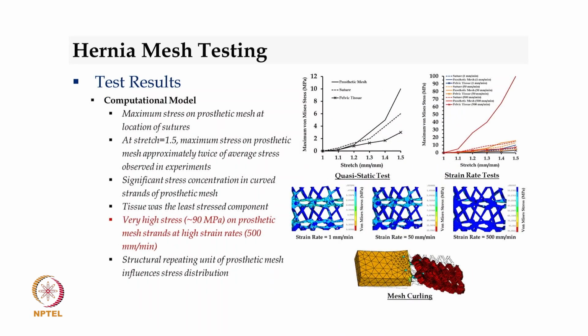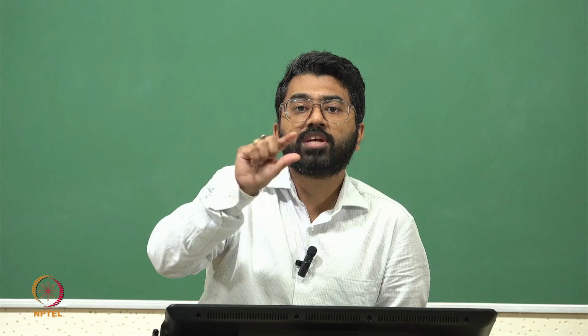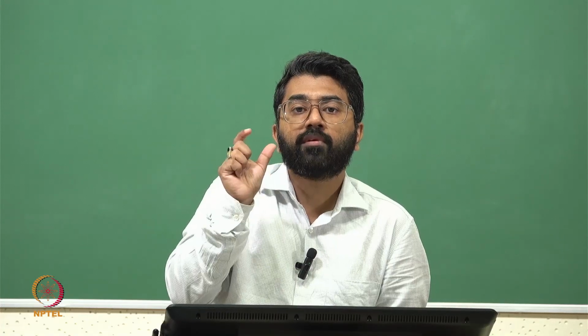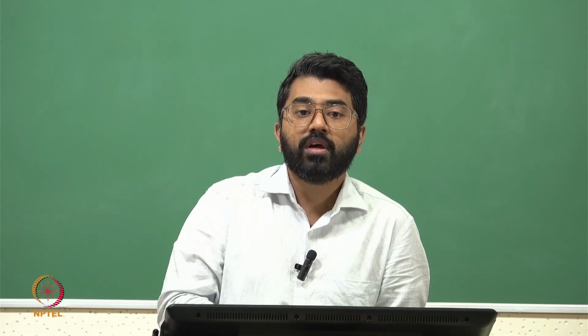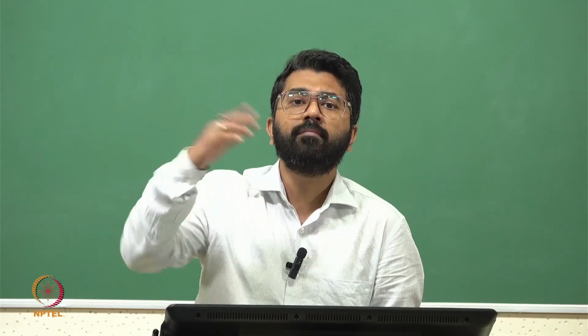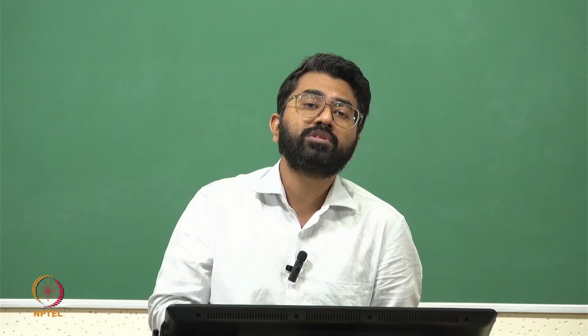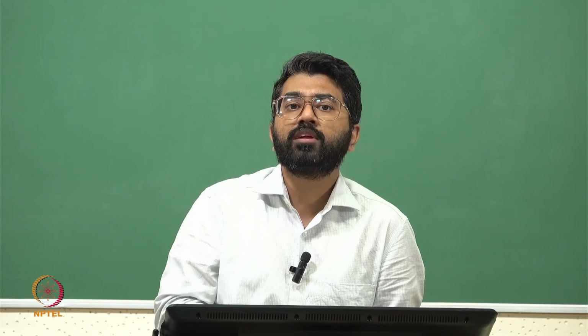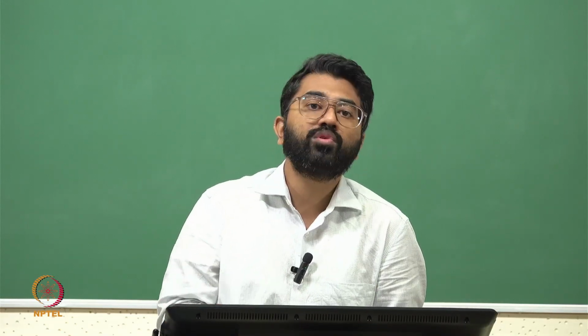So other things which we did find out, a very interesting result, we found out that there is a lot of stress concentration on the prosthetic mesh strands when we zoom in. This is through computational modeling, where, due to the unit cell, how the mesh is looking from a pattern standpoint, that is very unique. So this was a very key finding. The pattern of the mesh has a very unique implication on how the mesh could possibly fail. So this is a very important clinical information which a doctor would not know.